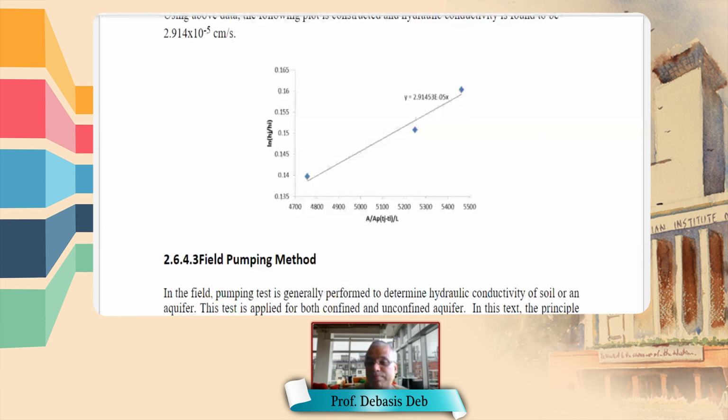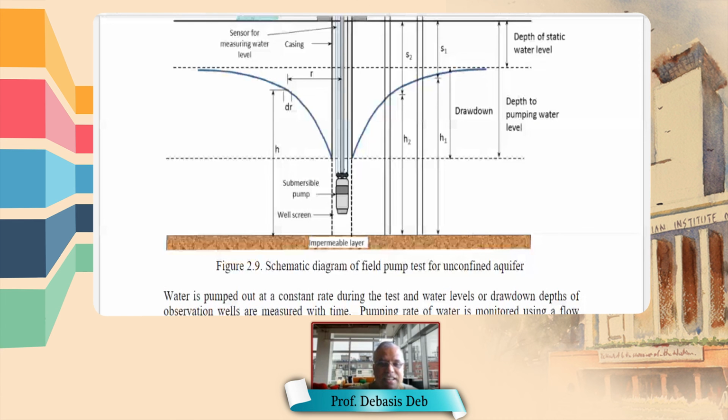So next time if the water is not coming in your house from the groundwater, let's say in a tube well or something, you will probably know what is the reason for this. It is the hydraulic conductivity which is causing the problem. Okay, because pressure difference we cannot change. It is not a pipe that I make a little bit inclined and make the pressure difference more.